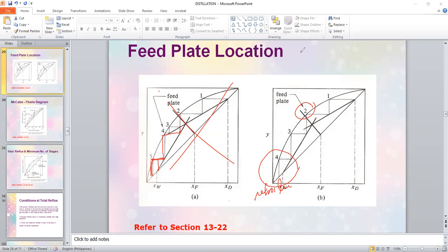And I'd like to erase what I have written because in here we don't say it's 3 or 4. We don't say the number of stages is equal to 4. Why? Because you did not rest here right on the X sub W. In terms of the area of the entire step here, you only cover this area. So as to what is the percentage of this area in relation to the entire step, that would be the corresponding number of stages here, including the reboiler.